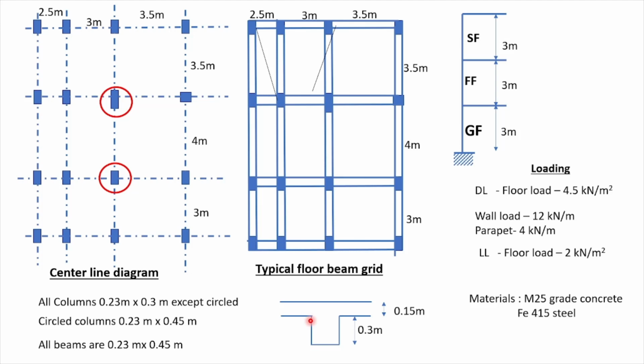That is how generally the sizes are fixed. I have taken the sizes randomly here, but there are a couple of procedures we have to consider. Sometimes by practice we see the span, estimate the load coming onto a particular column, and guess the column size, or do a rough calculation to arrive at the column sizes. If a beam has a length of, let us say, 3 meters, that is 9 feet.